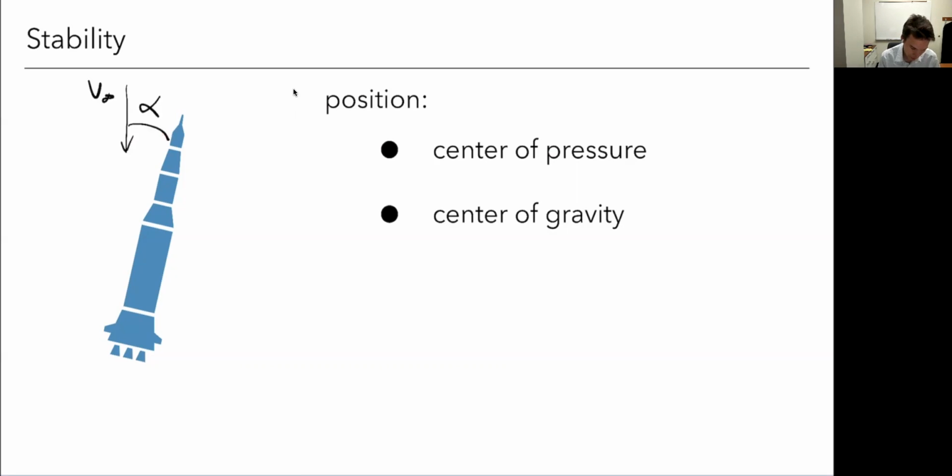So we already talked about the criteria, but let's just illustrate this again. So let's say here's my CG, my center of gravity. What are the forces acting on here? Well, imagine turning your head sideways. This is basically like a big plate or something going at an angle of attack. So I'm going to generate some lift perpendicular to V, and I'm going to generate some drag in the direction of V. And remember the right-hand rule, if I want to find a moment, that's going to be R cross F, and R is from the CG to these forces, so from here to here.